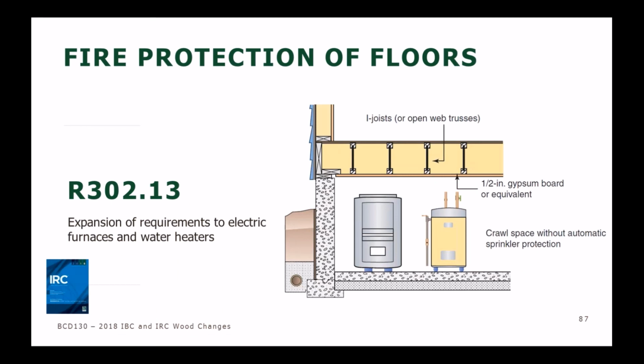We really don't have anything else right now. If you had multiple rooms within a basement, could you just have one room have the mechanical equipment and not do this to the rest? So that's not addressed. So I'm looking at the provisions in the code, and you're not able to add all the footnotes, obviously, to a slide. So it does deal with that 80 square foot area, and then some fire blocking requirements that would be along the perimeter that would sort of cordon off that space, I think, is probably the way to look at it.